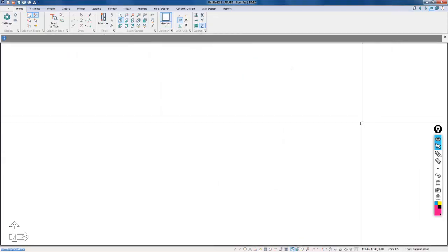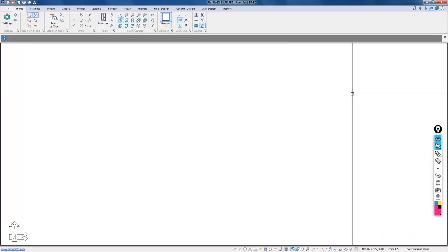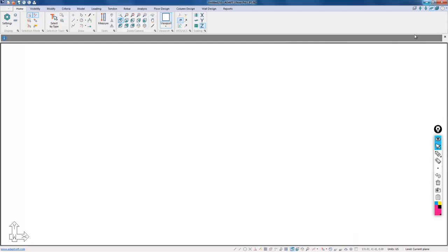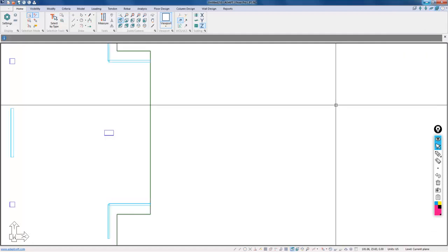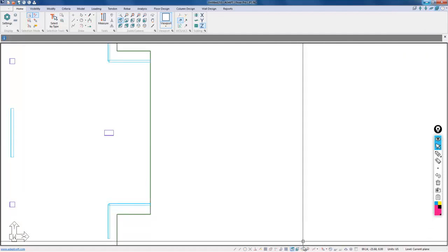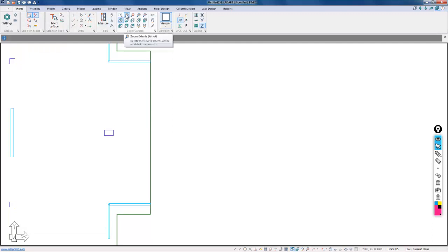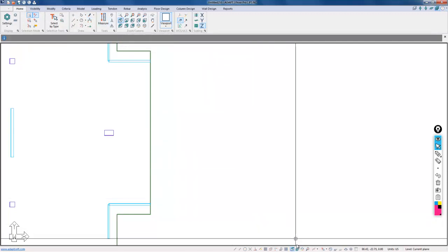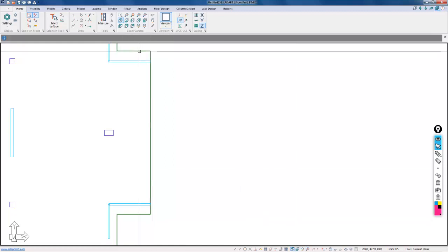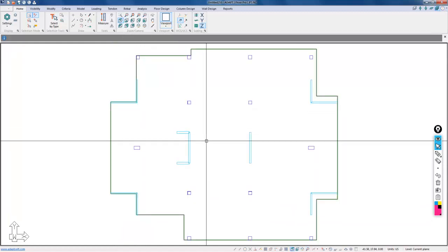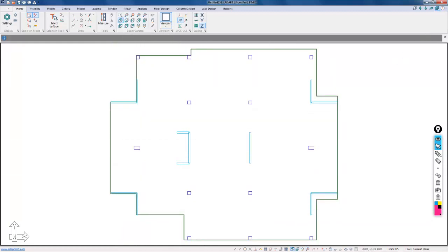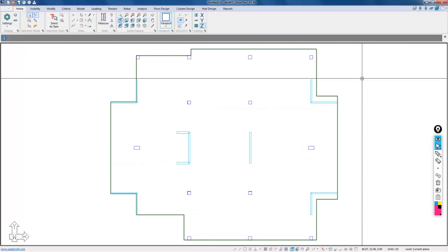If we select OK, we're going to go up to the top right, and I'm going to use multi-level mode. I'll select this, and then I'm going to use Zoom Extents. So I'll go to Home, here under Zoom Extents. That's also shown at the bottom Quick Access toolbar there. I'll select that, and you can see that this is actually showing every level in the sequence of levels.